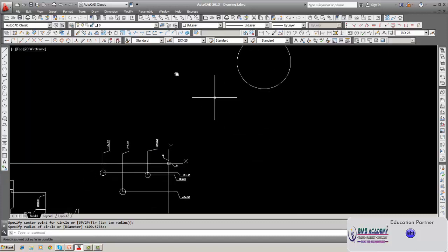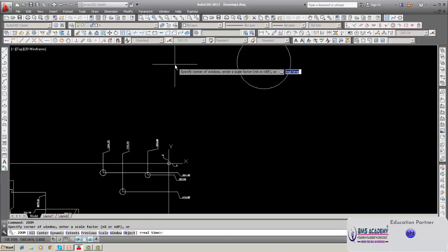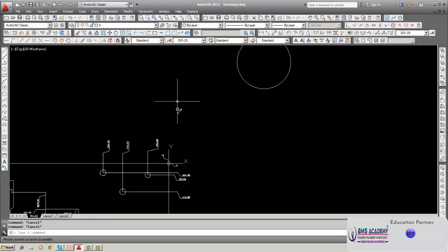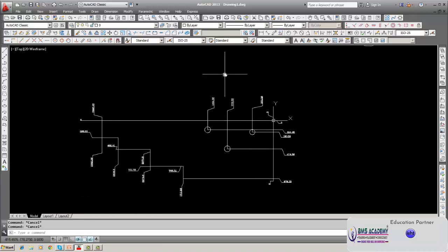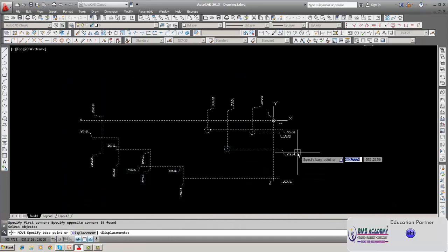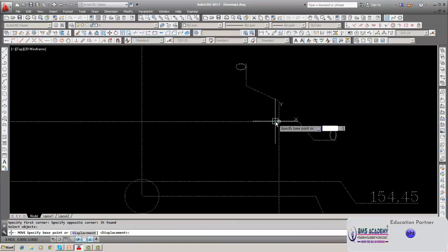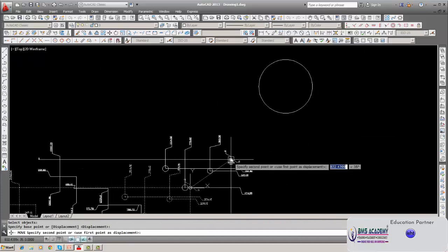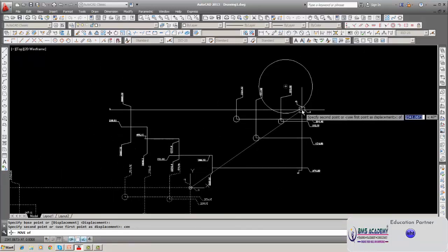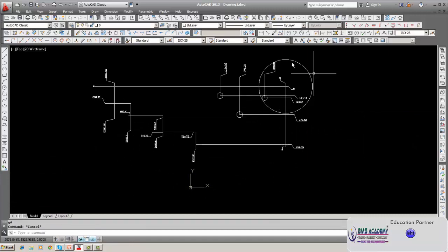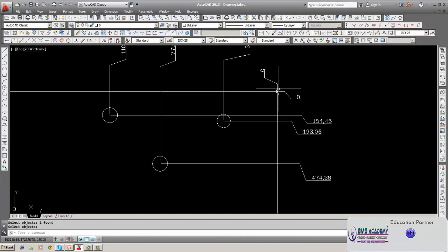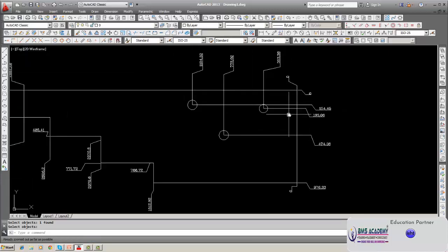Okay. Now you can shift the component to that position. So select the entire thing. Select the intersection point. Select properly. Then shift it here. Then you can erase. This is how we can do. Now see, the dimension remains the same. The item is selected and all dimensions are there. So I will sum up this. I will explain how we have done it.